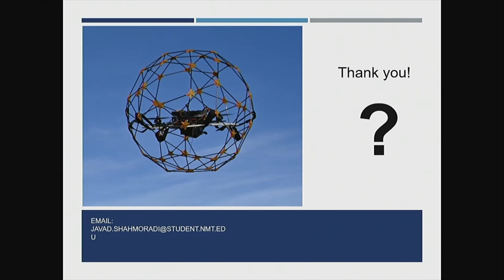With the cage and these sensors, it will be less than a normal multi-rotor, but it has advantages. A multi-rotor drone can hover somewhere and scan. For gas detection, we need our sensor to stay for some time, and for ventilation testers we need something like this. Ten minutes is enough for most mission work.